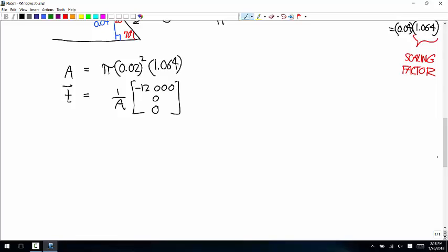So this is like how you would do this. I mean, this is a pretty practical way that this would all go. So you want to know what's happening in some loading using a certain material. So you take some amount of that material, form it into a sample, put it in the MTS machine, do the tensile test, use that to measure Young's modulus and the strain, and then put those values into your calculations. That's the idea. It would have made more sense if I would have referred to the correct numbers.